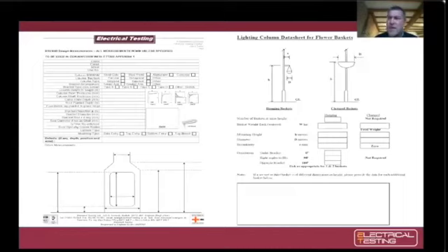So a series of non-destructive tests are carried out, and then we take the measurements with regards to bracket projection, bracket diameter, and the bracket rise. And then if you look at the bottom, you've got a diagram of the column. We're measuring from ground level to the bottom of the door, top of the door, and to the shoulder and the top of the shoulder. So a lot of extensive work goes into collating information from site.